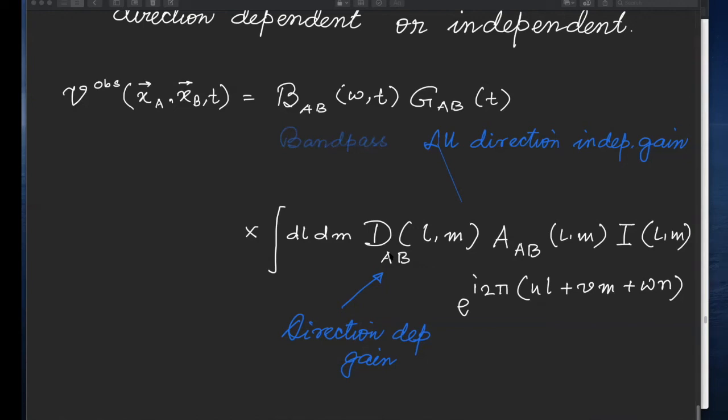So what I need is a local oscillator which will produce a standard signal that I can compare against. And making such a local oscillator which will radiate a noise signal at 2 meter wavelengths is extremely difficult. That's why GMRT doesn't have a single system temperature measurement. People have tried over the years, but I don't think there is any. If you go to the VLA, for example, you will get the system temperature values. They're at much higher frequencies, and you can use the noise source.